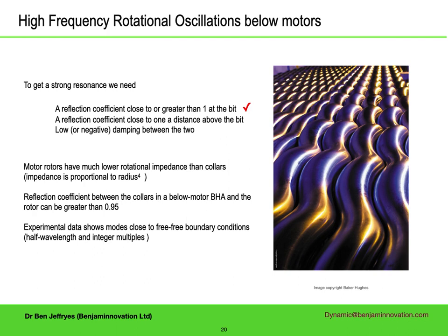We had some pretty good evidence that this is the right boundary condition from measurements made in a test well while casing drilling. This was done with quite a long assembly, and measurements of both torque and rotational acceleration. The resonances of the system could be simulated assuming different boundary conditions and compared with the measured data. There was a high level of vibration in the assembly, though no stick slip. There were multiple resonances, and they matched extremely well to a free boundary condition.